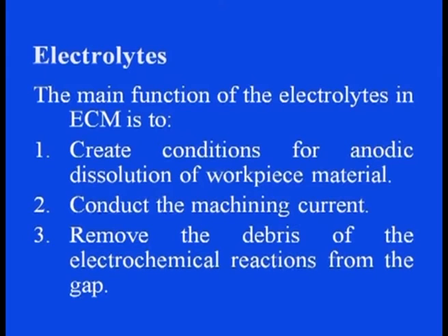Then number 3, remove the debris of the electrochemical reactions from the gap. This also we have discussed already. Number 5, carry away the heat generated by the machining process, thereby maintain a constant pressure in the machining region. And therefore, a number of characteristics have been listed out for performing these functions.